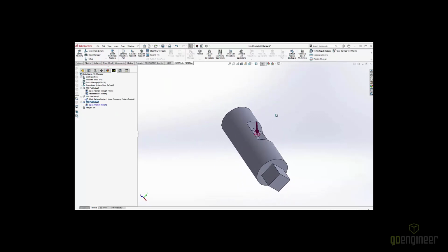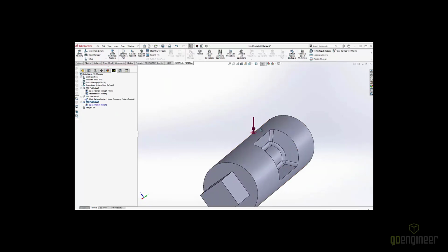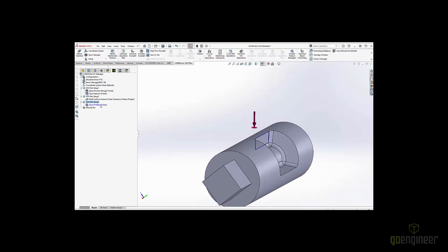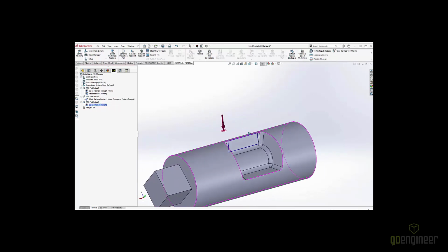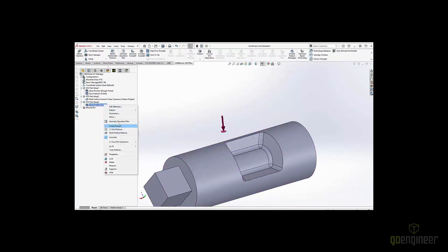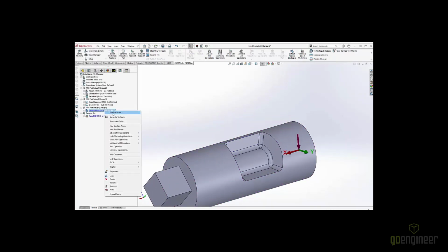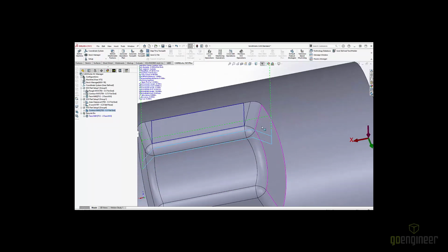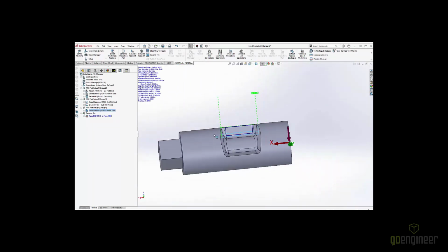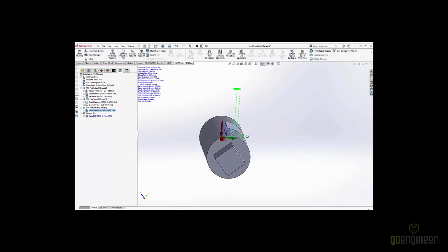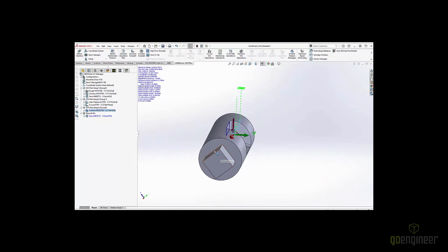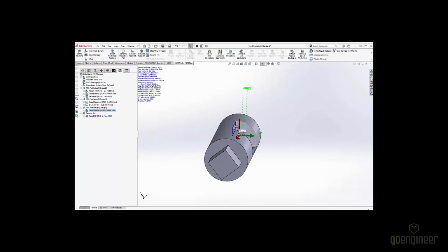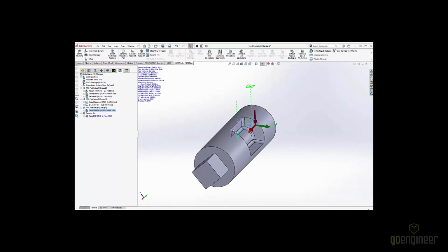I actually had a setup created. I guess I had it on the reverse side. But now you can see my tool orientation coming down. I've got an open profile feature created there. I could go ahead and program that. I have some lead ins, lead outs that I could modify, make sure I'm not gouging. But that would get me the best surface finish there, but it'd be very difficult to orient the part in this orientation in a vise and really know that I'm lined up correctly. So I'm a little limited there.